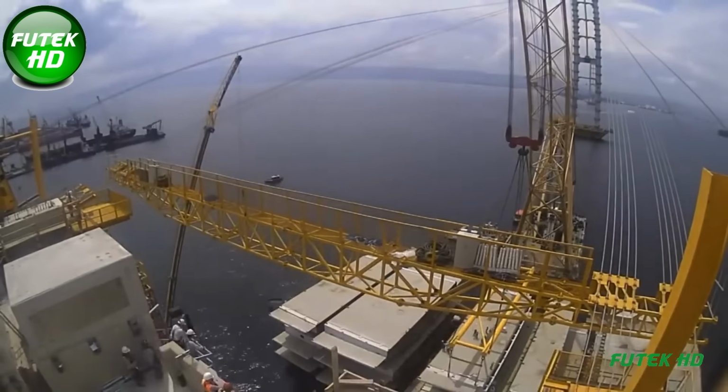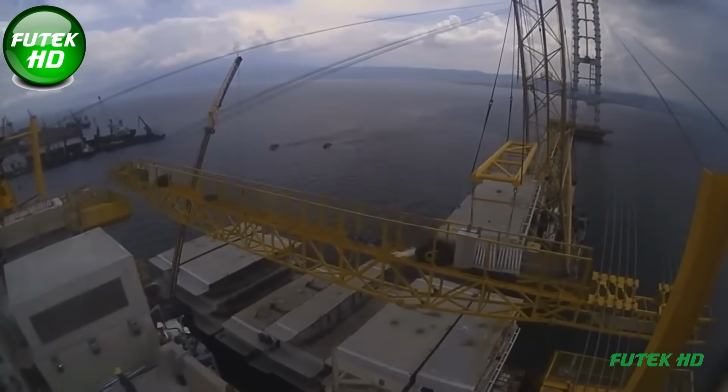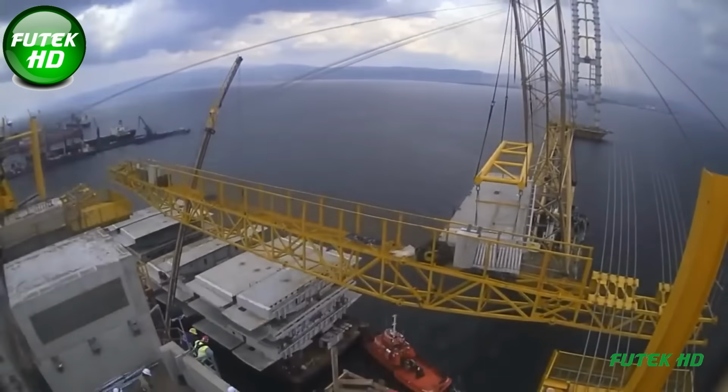With the main towers and cables in place, the final structural component was the stiffening girders, which create the road deck on which vehicles travel. The stiffening girders feature a flat, hexagonal cross-section, a design chosen for its superior resistance to wind-induced vibrations. The construction team used different methods to lift these girders into position.